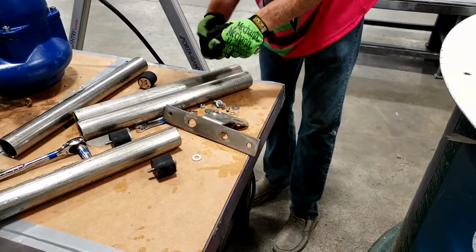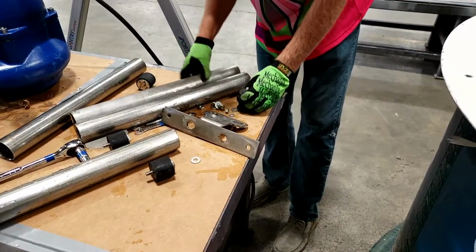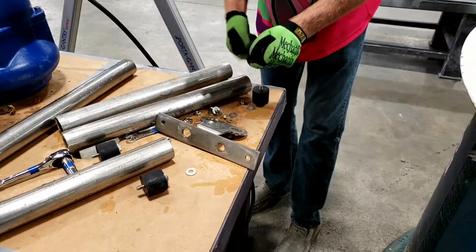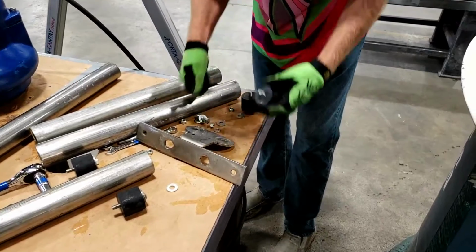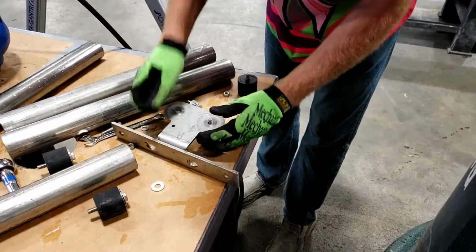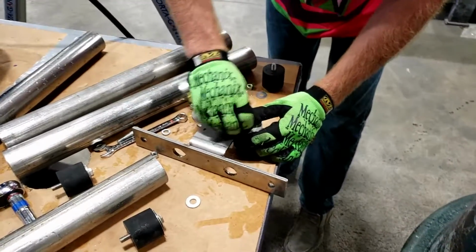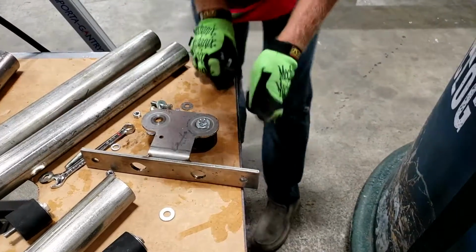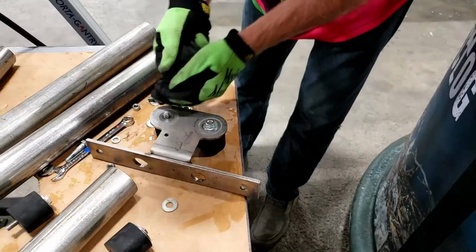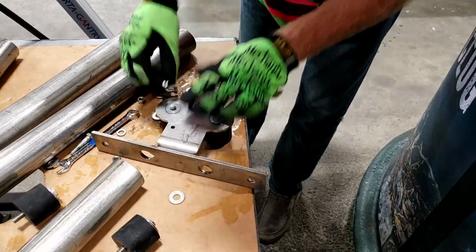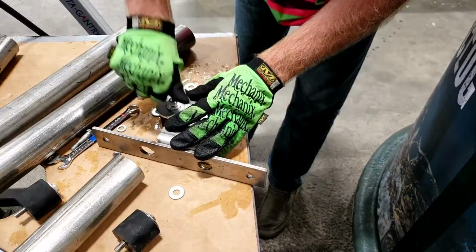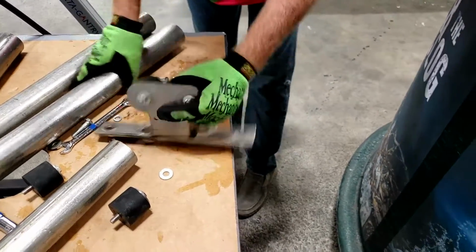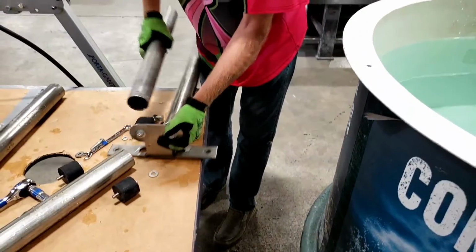Install new rubber compression fittings and new 2-inch stainless steel guide rails on the guide rail flange. The rubber compression fitting shall be installed such that the nut side of the bolt is what is showing through the guide rail flange. Rubber compression fittings shall be tight enough that the rail does not slide up and down. You can now install the guide rail and flange back in the wet well.